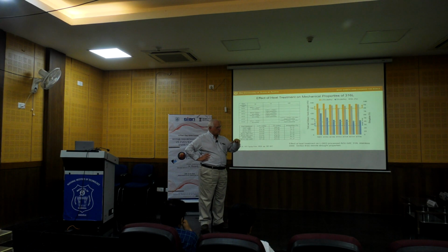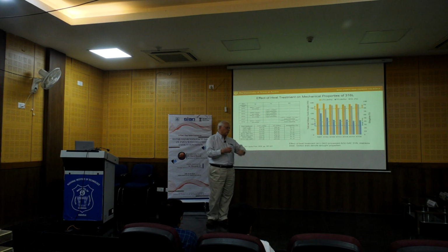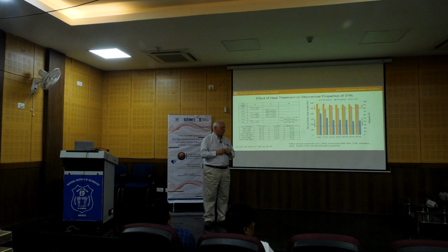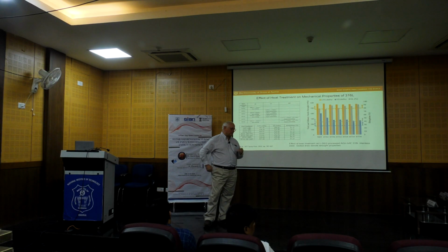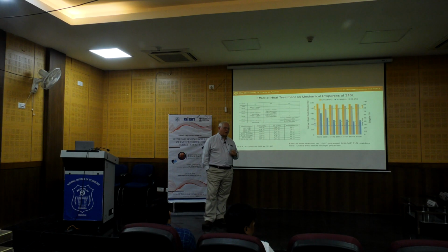Re-sieving is a classification technique where we pull out certain size particles. We can separate out the coarse particles, which would be almost all of the satellites, from the rest of the powder, throw them away, and use the fine particles. It's a relatively straightforward and inexpensive approach. I don't think it will completely solve the problem, but it certainly would help.